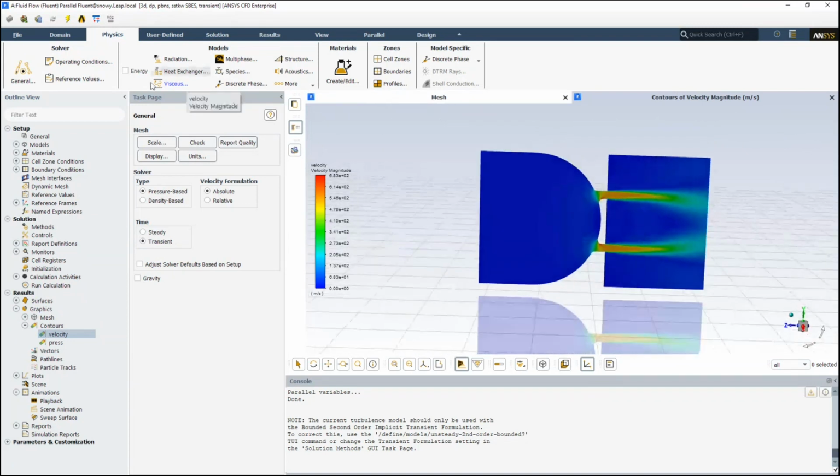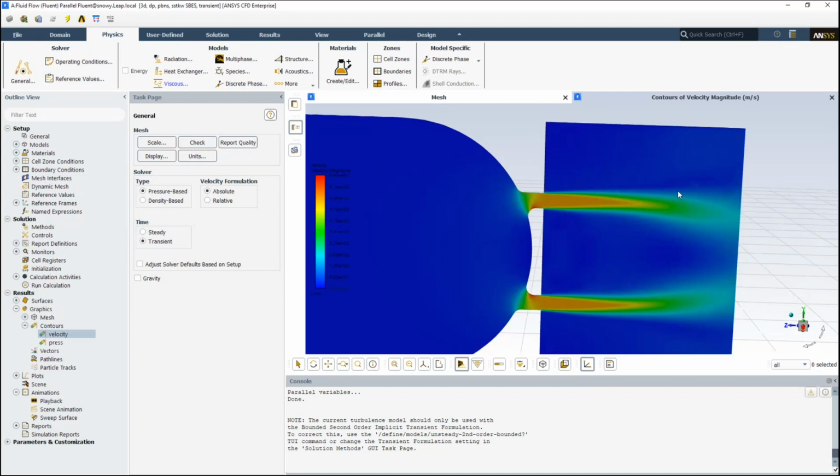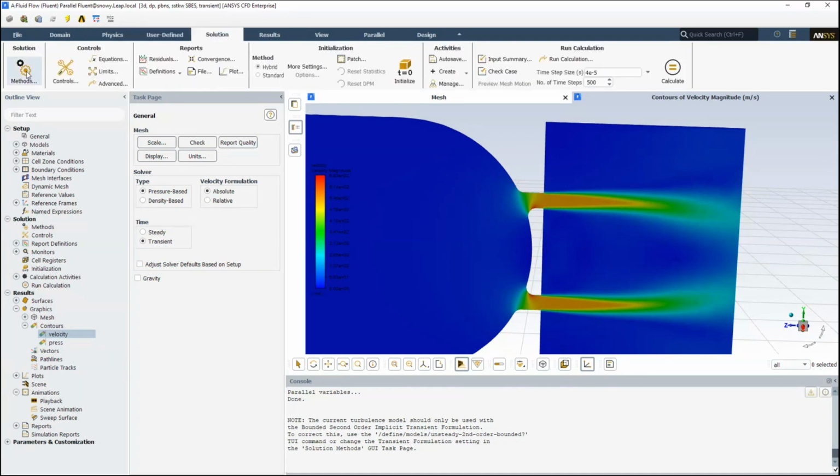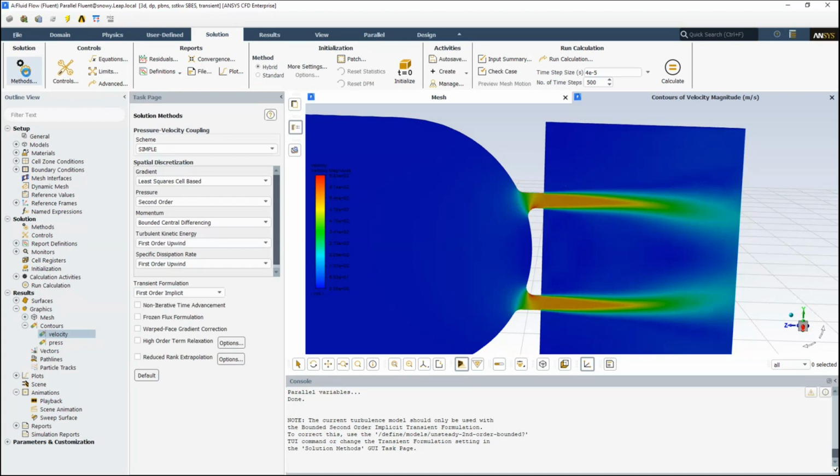Okay, so we can see here, this is run just k-omega SST, steady, right? And obviously you can see here we've got our flow coming in. There's not really any kind of chaotic phenomenon being picked up. And then we turn on, that's our start point. So we've got this solution in here. We turn on our SBES, and then we run transient from that point.